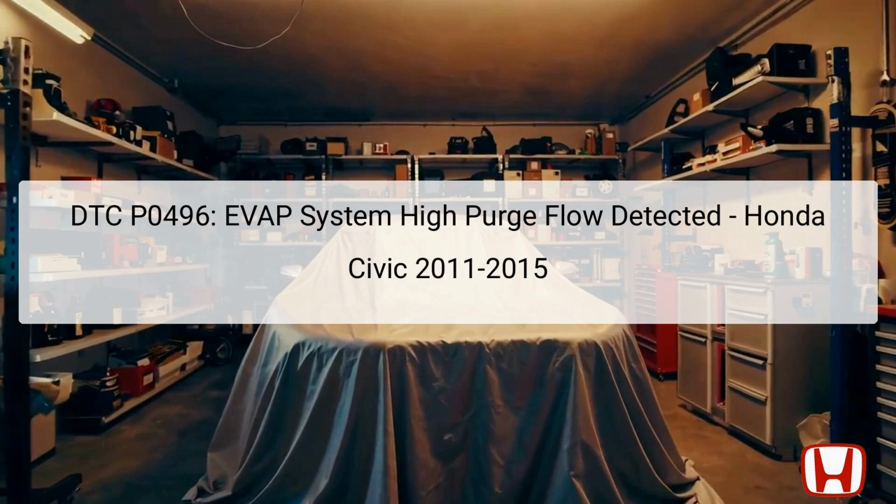DTC P0496 refers to a diagnostic trouble code indicating that the EVAP system has detected high purge flow. The EVAP system, or Evaporative Emission Control System, is responsible for preventing fuel vapors from escaping into the atmosphere. This system includes components such as the EVAP canister, purge valve, and fuel tank pressure sensor.